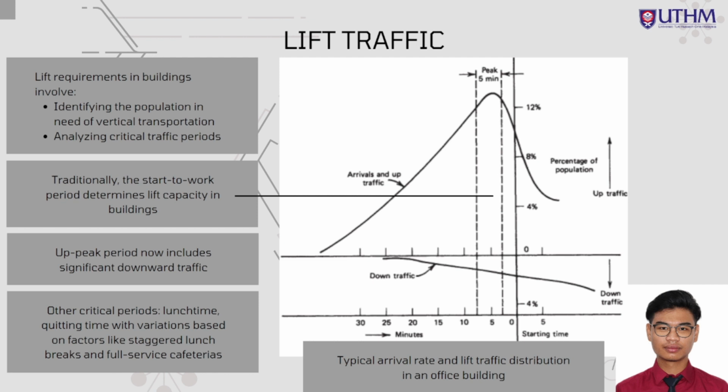The lift requirement in buildings involves identifying the population in need of vertical transportation or lift and analyzing the critical traffic periods. Traditionally, the start-to-work period determines lift capacity in a building, and now the off-peak period also includes significant downward traffic.